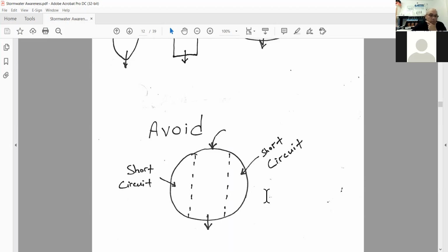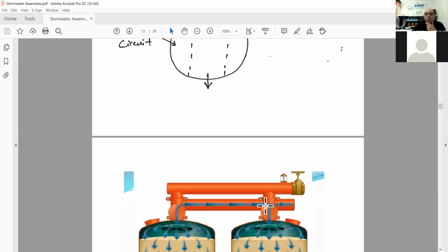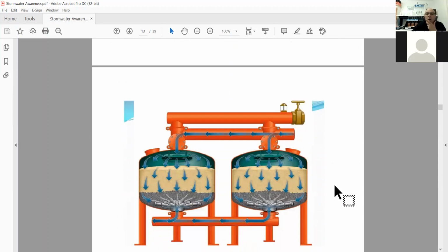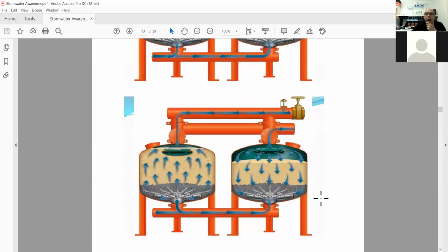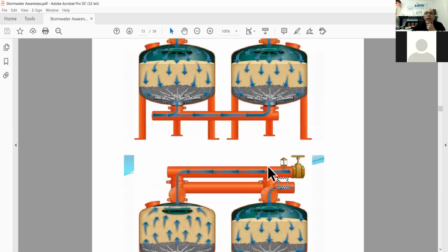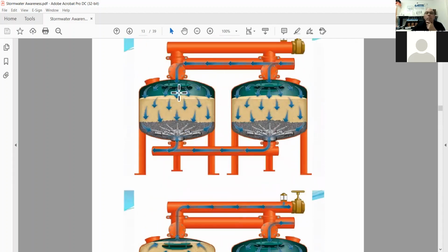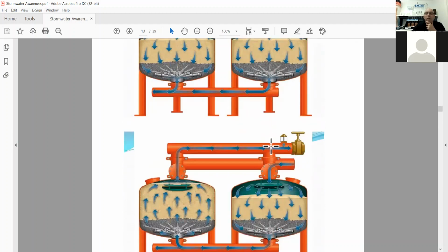Water is then pumped from the overweir side, the opposite end of the pond, usually at about 100 NTU water clarity, and then the water is filtered. And so here's filters shown. Here's the backwash shown. So reverse the flow. The influent water is still coming through into the filter like it did here, coming into both filters and coming out the bottom to discharge.